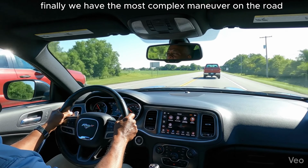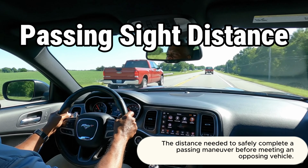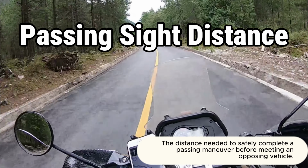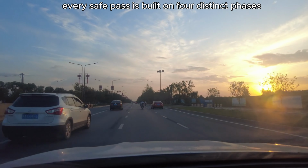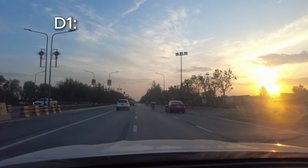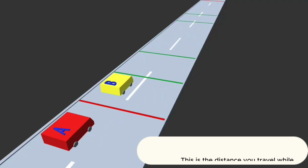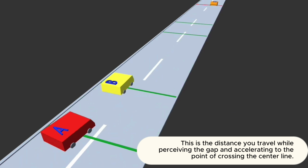Finally, we have the most complex maneuver on the road, the passing sight distance. It is the distance needed to safely complete a passing maneuver before meeting an opposing vehicle. Every safe pass is built on four distinct phases. First, D1, the initial maneuver. This is the distance you travel while perceiving the gap and accelerating to the point of crossing the center line.